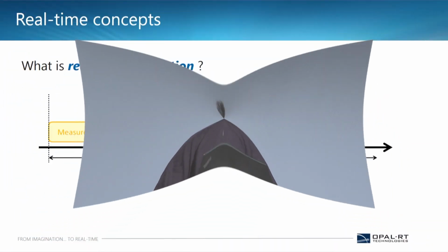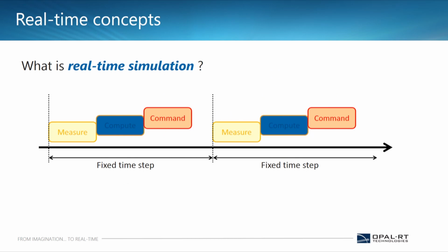Now, talking about real-time simulation, this basically works on fixed step simulation. Since we are dealing with the MATLAB Simulink platform, I'll be talking about MATLAB design parameters. In MATLAB, if you go into the configuration settings, you will see there are two types of solvers used: fixed step solver and variable step solver. Real-time simulation is only about fixed step simulation.